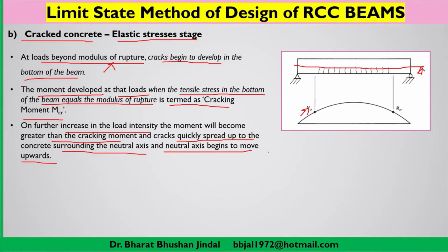So later on you will be able to understand the meaning of this neutral axis movement. At this time we can understand that when you are increasing the load, a moment will develop, and as soon as the moment reaches the cracking moment, some cracks will develop at the bottom of the member. That means tensile stresses have developed.